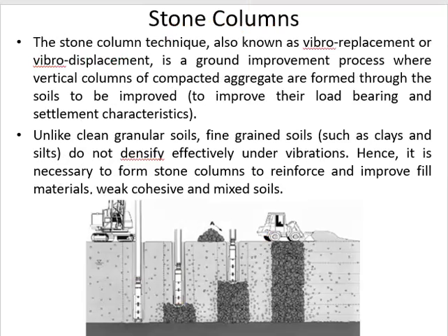So what are these stone columns? The stone columns are nothing but boreholes which are filled with aggregate. The stone columns are useful to densify the fine grained soils where compaction is not effective. These stone columns not only provide drainage path but also provide lateral support like reinforcement and improve the strength of fine grained soils.